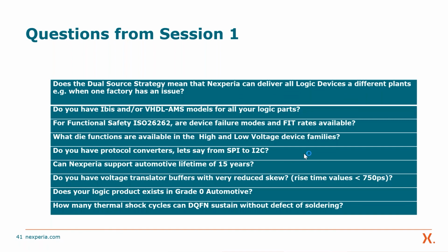Oh, it's actually advice from one of our own application engineers who is already jumping into it. It's recommended to use high reliability solder for mitigation of effects due to thermal balance. So it is outside of the package itself too. And again, we'll get you that information. That information exists. It's putting it together to determine the best way to avoid a thermal or a vibration shock for our devices.